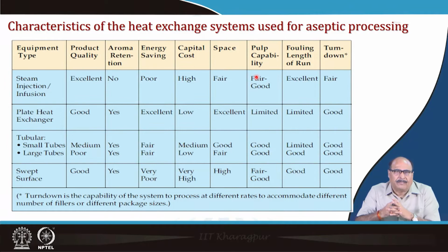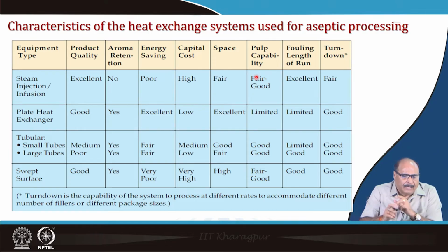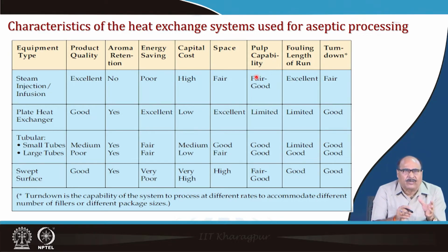So, in this table I have tried to give you a comparison of various types of heat exchangers. For example, the steam injection or steam infusion heat exchanger, if you see, as far as the product quality is concerned, they are excellent, but there is no aroma retention, so most of the aroma gets destroyed.